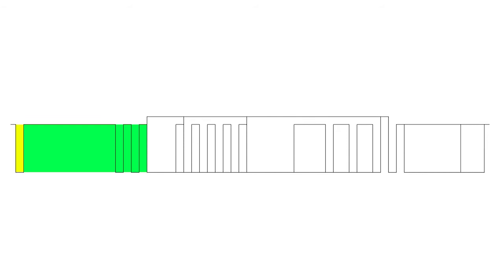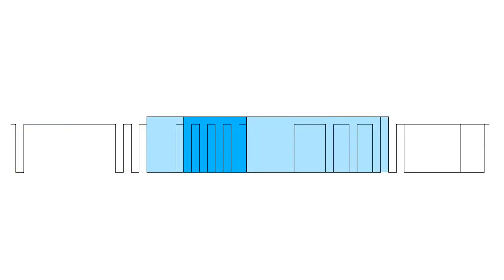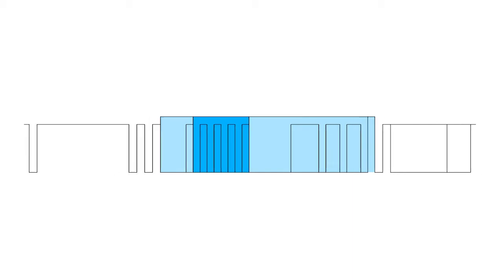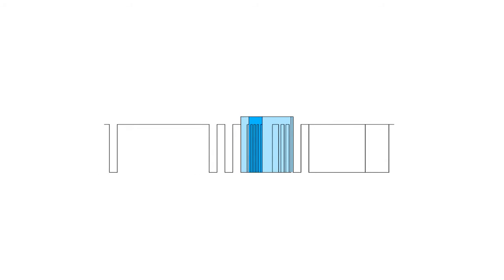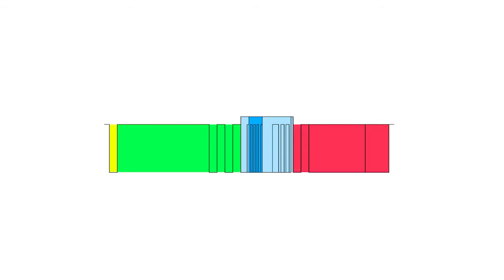CAN's limited bitrate ensures that arbitration works successfully in the first part of the CAN frame. The data section after arbitration is sent by one single unit. And when there is just one sender, it is possible to increase the bitrate. This possibility available in CAN is utilized by the CAN-FD standard. The beginning and the end of the CAN frame will keep the arbitration CAN bitrate to secure the real-time performance. This is the main difference between CAN and CAN-FD.